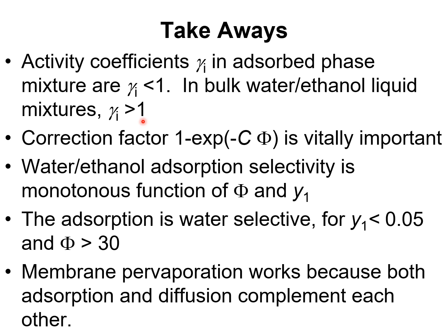So never use the NRTL parameters fitted for water ethanol liquid mixtures to estimate the activity coefficients in the adsorbed phase mixture. The results would be worthless and also meaningless.